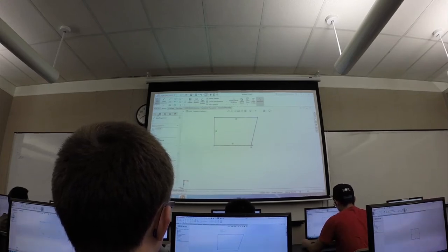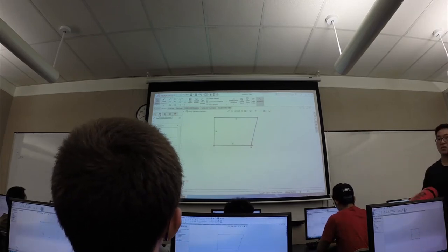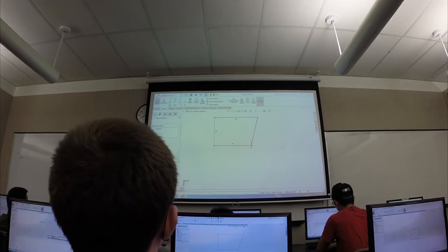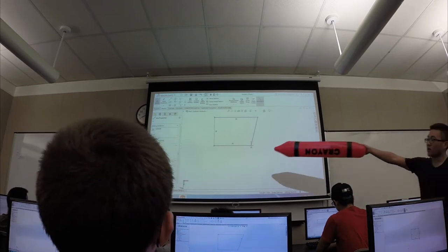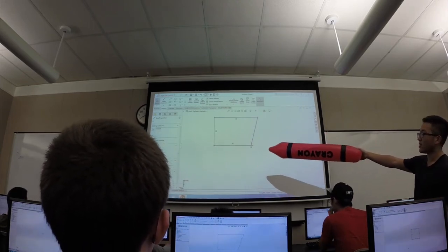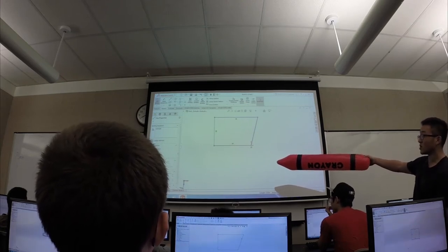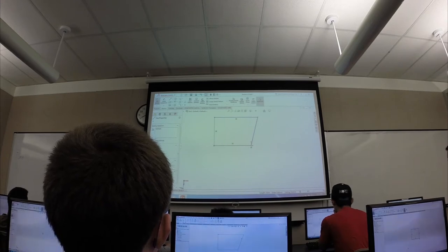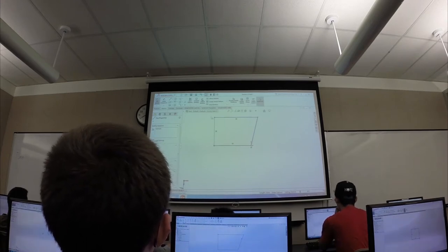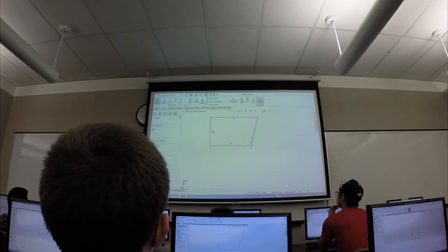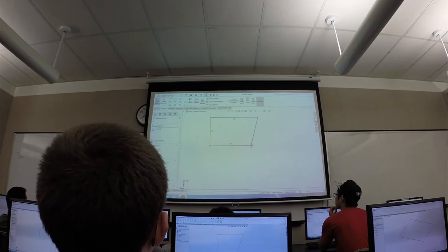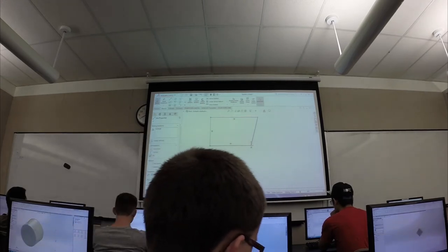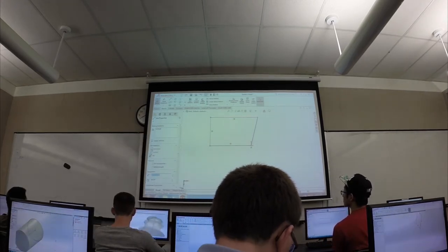If you click on this line, you notice that the Properties tab pops open automatically. This is where you can start defining some parameters for your line. Down here in the parameters, you have your length option and your angle option. Right now it's at a random size of 3.0321 inches at a perfect 90 degrees. Also, you can lock in relations here. If your line wasn't perfectly vertical or horizontal, you can click on these relations on the left pane, and it will make them in that direction.